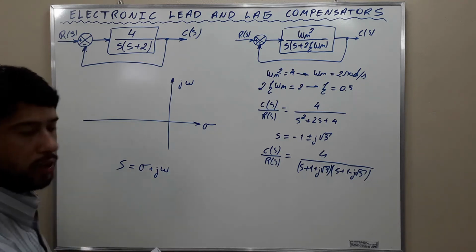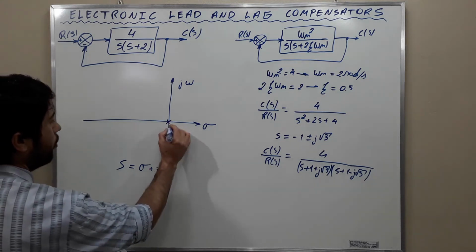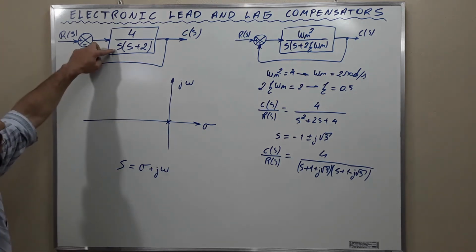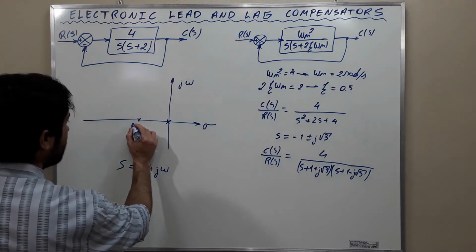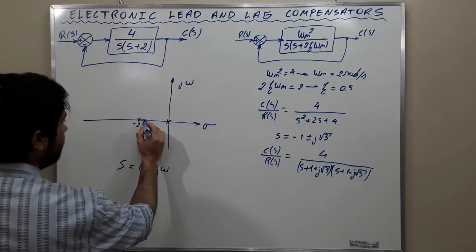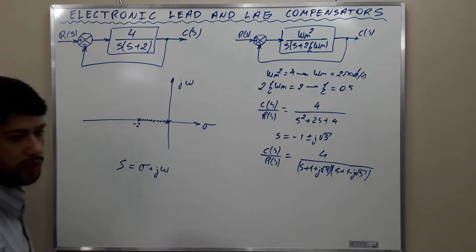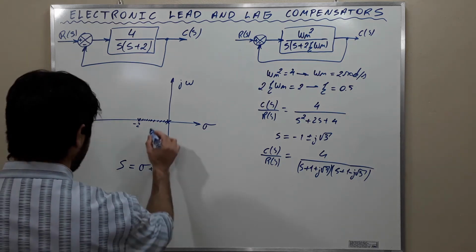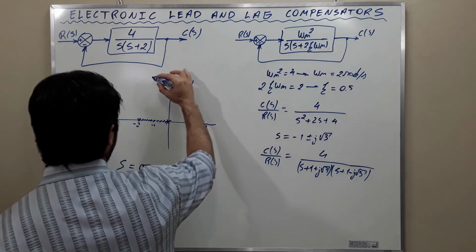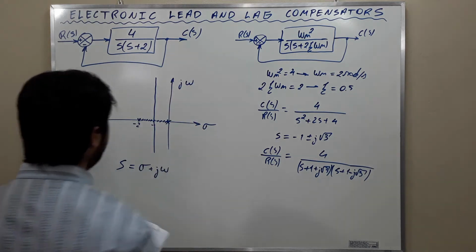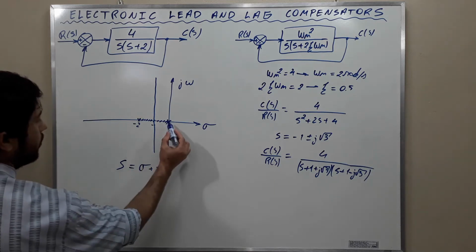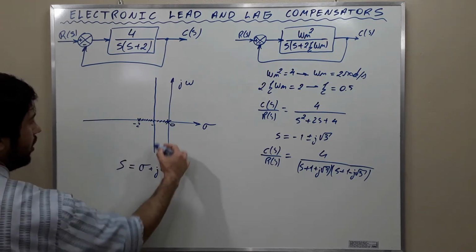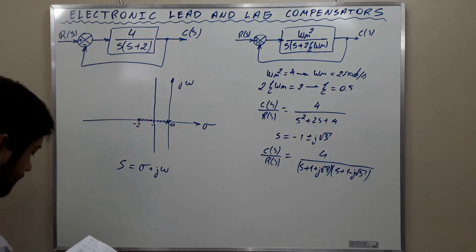And the root locus is going to be, we have a pole at 0 and an open loop pole at -2. And this is part of the root locus, and we have a root locus here, -1 here, and this is the root locus plot of the system from 0 to -2, and this line here, okay?